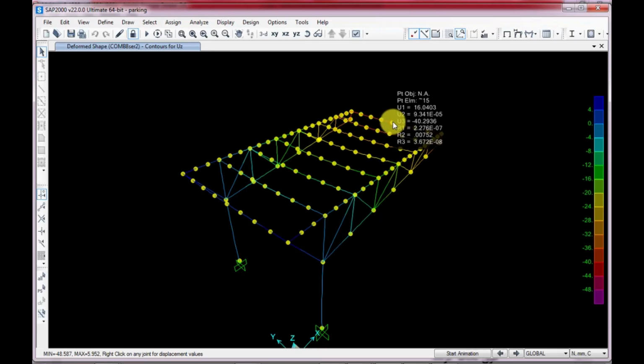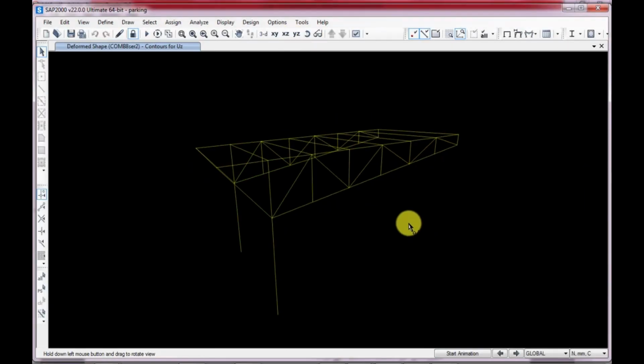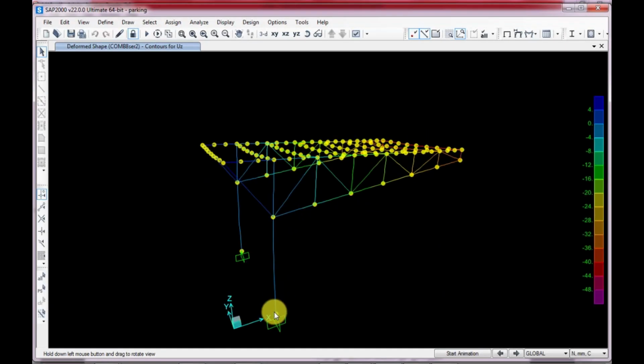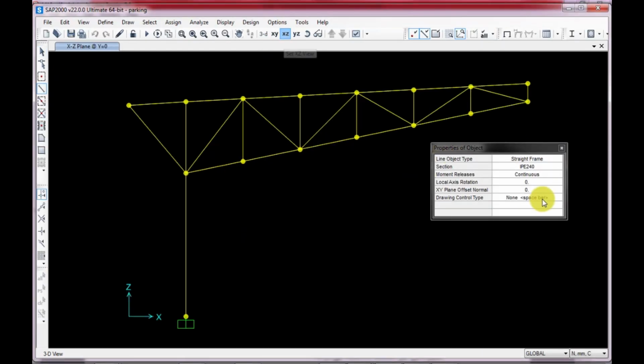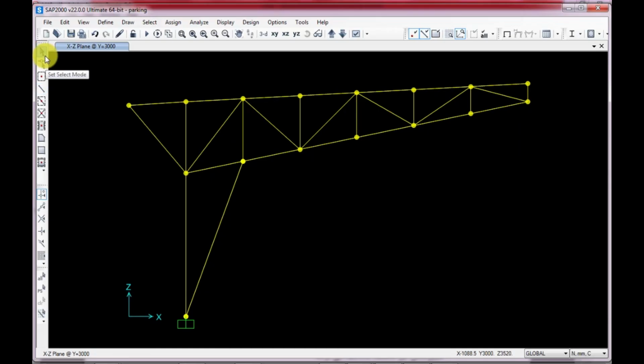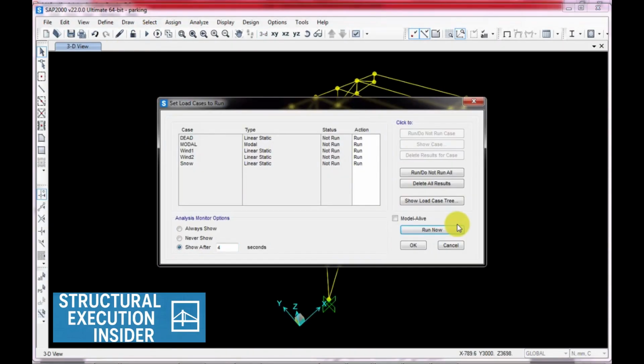Now that the structure has passed both strength and displacement checks, we move to the overturning stability verification. For lightweight structures such as canopies, wind-induced overturning is a critical design case. The structure must remain stable against uplift and lateral wind forces.